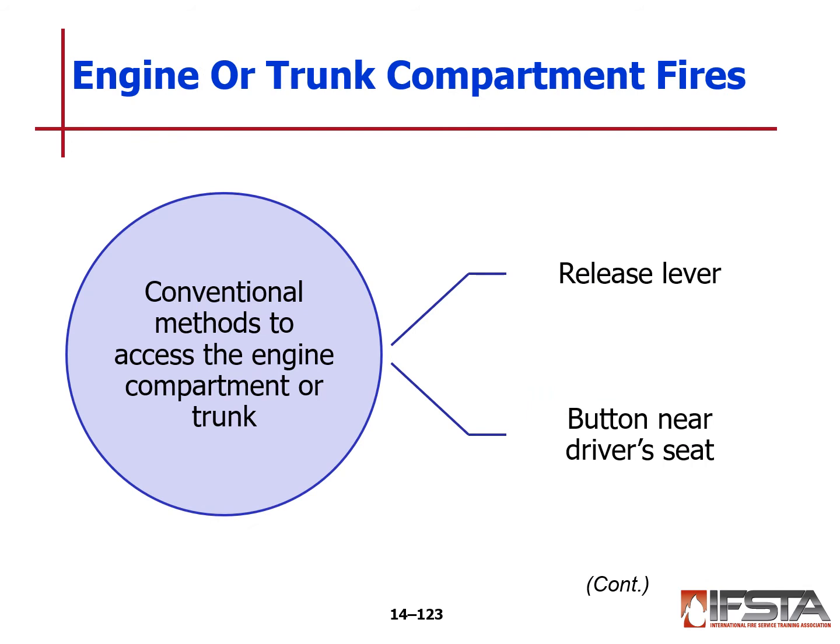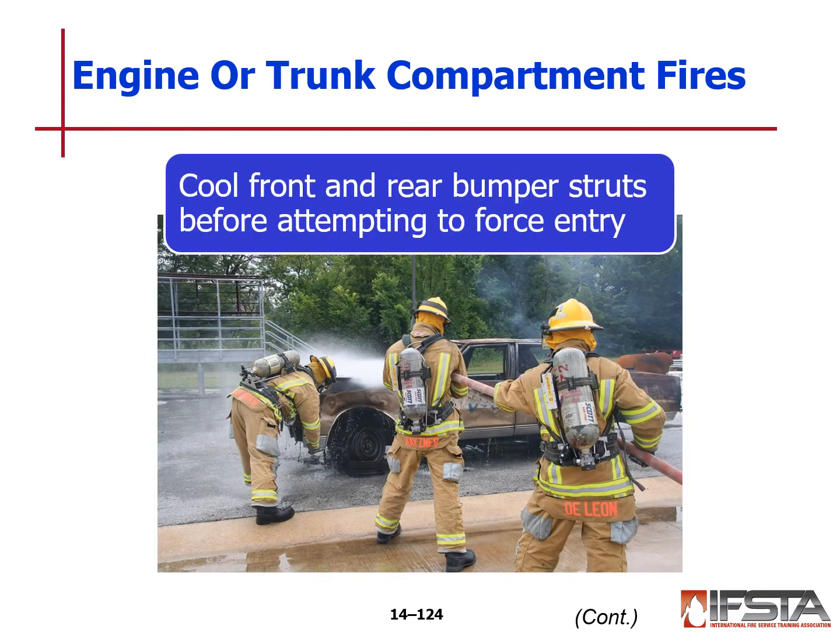For engine compartment and trunk compartment fires, conventional methods to access these compartments could be using the release levers. Usually those are cable driven, and if they have not been damaged by the fire, this does work if we can get inside the vehicle, if it's not involved as well, and activate these. But it also can be a challenge, and so we want to cool the front of the car.